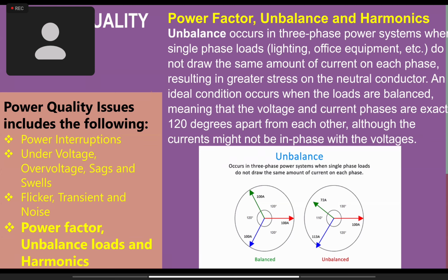And to other loads, it can create heating. Kasi pag magkaroon tayo ng voltage unbalance, magkaroon tayo ng unbalanced load, yung voltage drop on other parts of the system could be higher than the other phases. So as a result, pagka hindi naman balance yung voltage mo because of the varying voltage drop, it will create heating to our electrical equipment, specifically the motors. Kasi ang percent unbalance lang allowed for the electric motors is 5%. So anything beyond 5% is not advisable. So kailangan talaga i-balance.